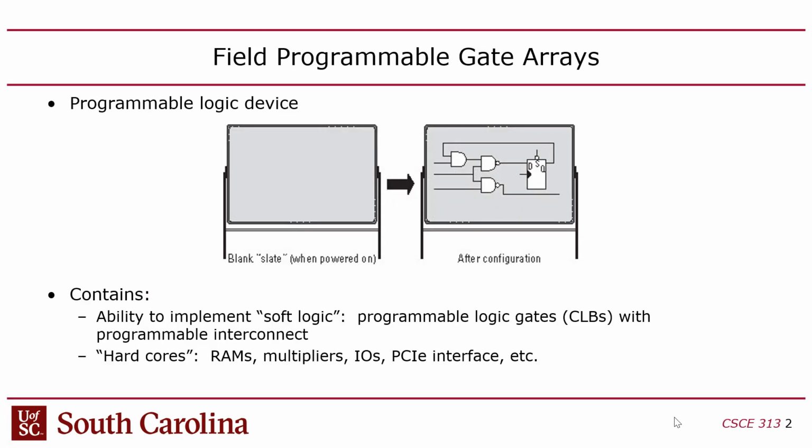So first of all, in case you're not in 313 and you haven't taken 611, an FPGA is a field programmable gate array. It's a chip that's basically a blank slate. It's useless when you power it on. It does nothing. It's basically a paperweight until you configure it. So you electronically configure it to act as an arbitrary digital logic circuit, right? So you do a hardware design, and then you put it on the FPGA, and the FPGA takes on the behavior of that logic circuit.